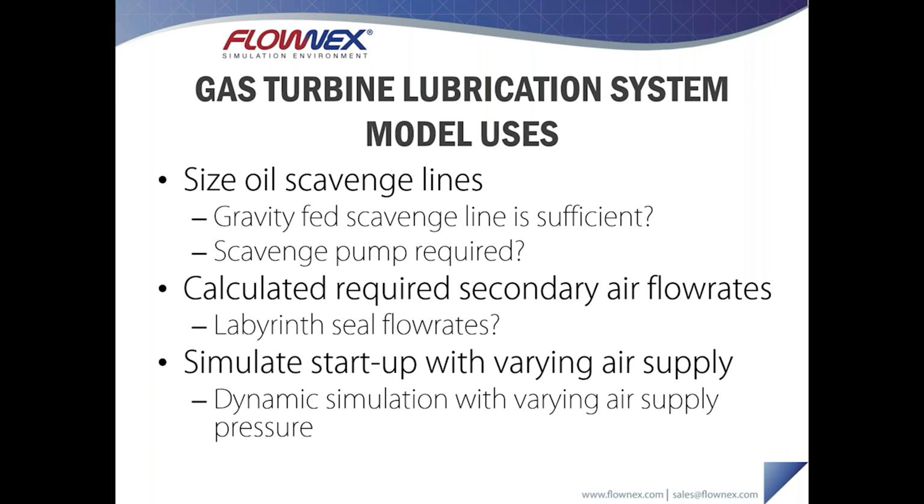And then also looking at sizing the vent lines. In the case that you have a bearing chamber that has an air vent, sizing that vent line is important to ensure that the level inside of that particular chamber is at the value that you would like.